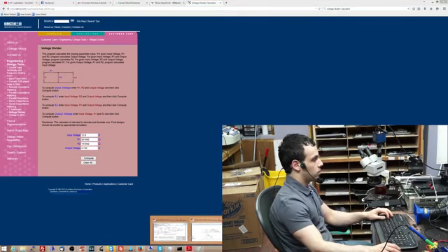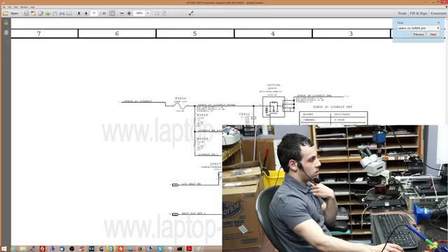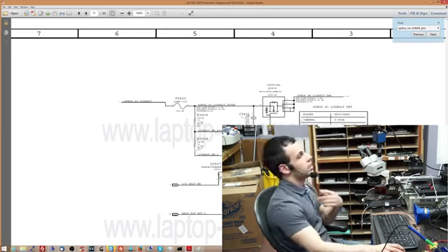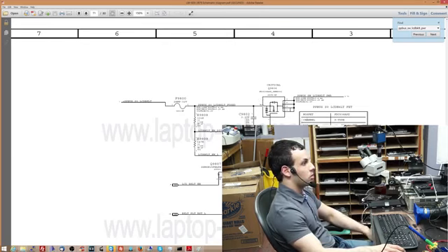So here's the way this works. When this LCD backlight enable is not coming in, this transistor is closed. So therefore, this does not have a path to ground, so this will not work as a voltage divider, which means that 12 volts is going to be on the gate of this P-channel transistor. If there is an equal voltage on the gate of the P-channel transistor as there is on the source, power will never flow to the drain and the light will never turn on.